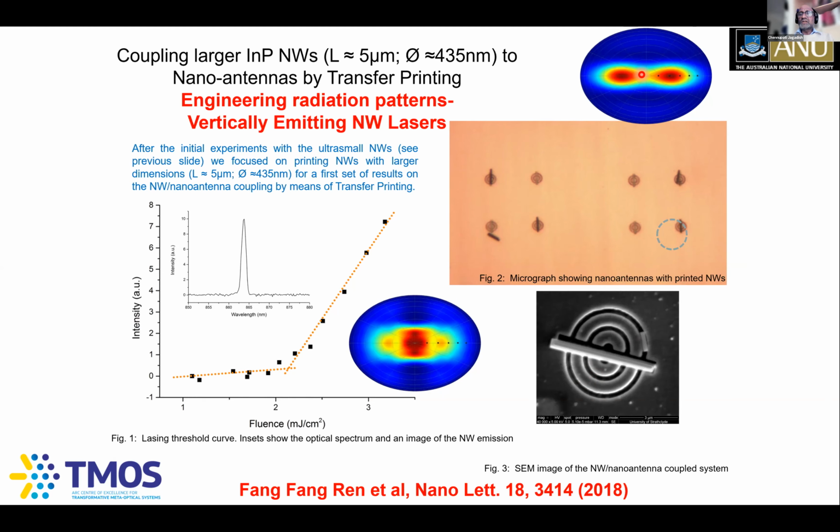Whenever you want to couple light to an optical waveguide, you make use of these edge-emitting lasers, which are Fabry-Perot cavities. And whenever you want the light to come from the surface of the substrate, you make use of these nano antenna coupled nanowires, so you can use them as vertically emitting lasers. For example, if you want to use them for meta-optics applications, you want coherent light sources, or even facial recognition applications. Those of you who may be using some of the Apple phones and others, there's a facial recognition system made out of vertical cavity surface emitting lasers. By using vertical emitting nanowire lasers, our hope is that you'll be able to use very limited space and also consume less energy. That means your battery can last for a longer period as well.